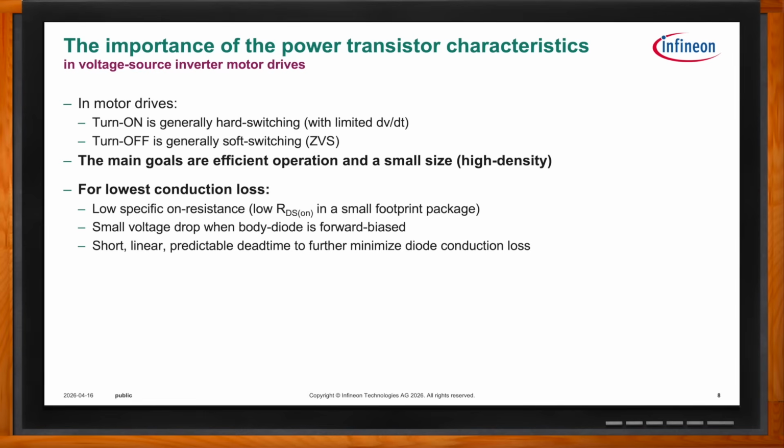But when the transistor is during dead time between one phase turning off and the other turning on, sometimes you're in diode mode in these transistors, and you have effectively a forward biased diode, and that can be a much larger drop. We might be talking tens of millivolts, hundreds of millivolts when it's in the on state in the regular forward direction. In the reverse direction body diode mode, it could be volts.